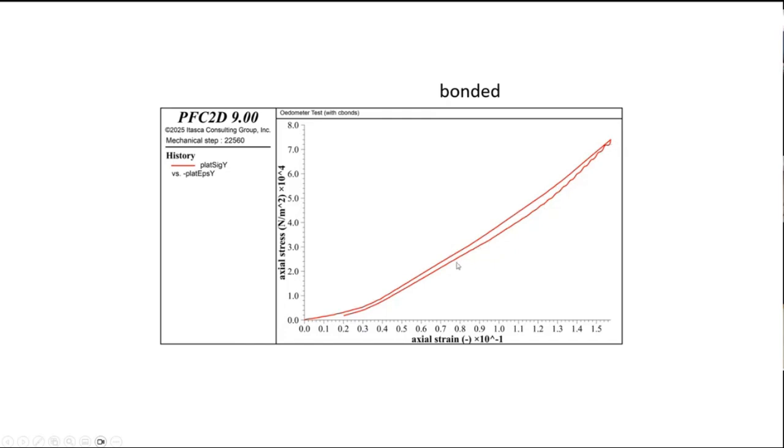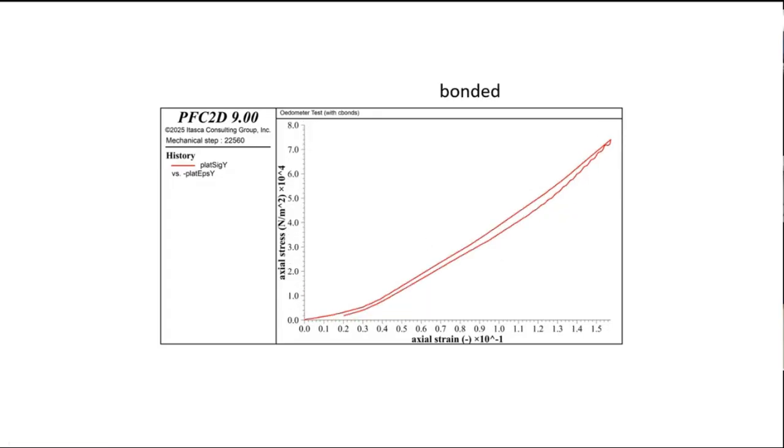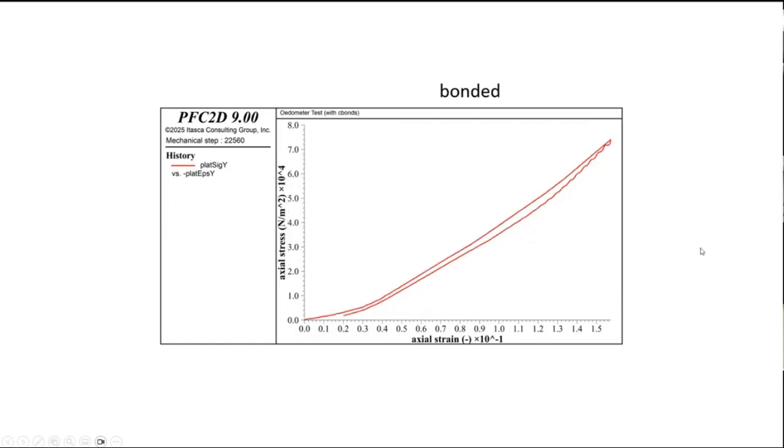And now we're unloading it. What's the other thing about energy between these two systems? Look at this one. Less energy. Yeah, energy loss. I would agree. I mean, we'd have to quantify it, but I think that's the case. This is a bigger hysteresis loop. This is a bigger difference when it's unloaded. There's a lot of energy loss in the sliding. There's no sliding. Well, now let's try to unpack this.